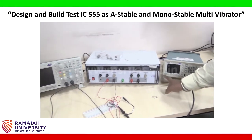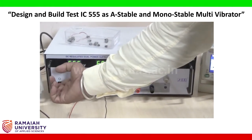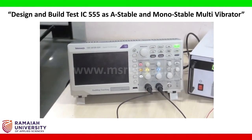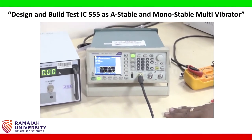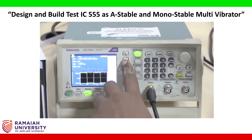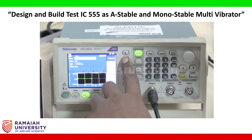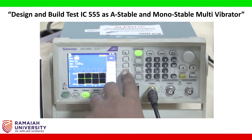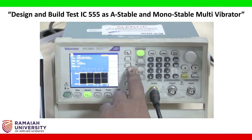Now I am going to switch on the signal generator, the DC dual power supply regulator and the digital oscilloscope. Now I am going to adjust this to a square wave with the frequency, just click on frequency, of 300 Hertz, and I need to fix the amplitude. So just go back and click on the amplitude.